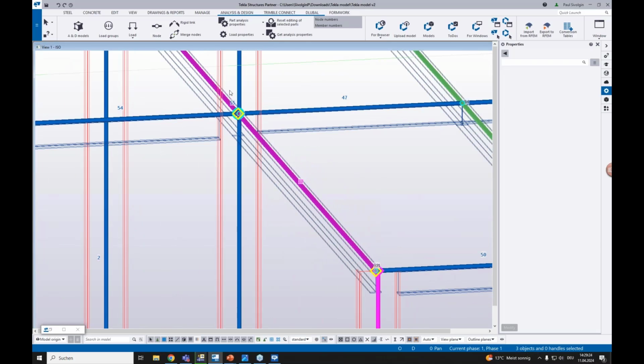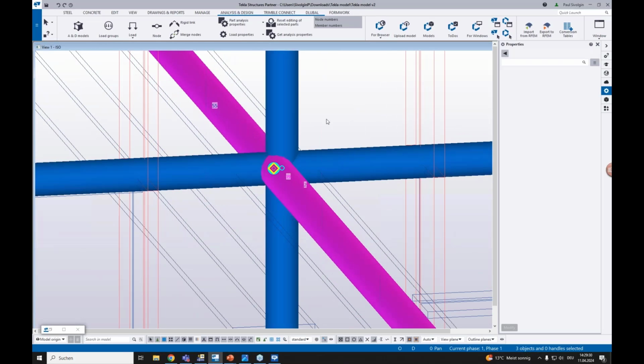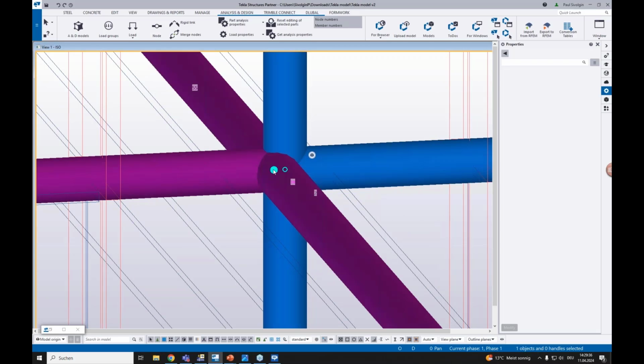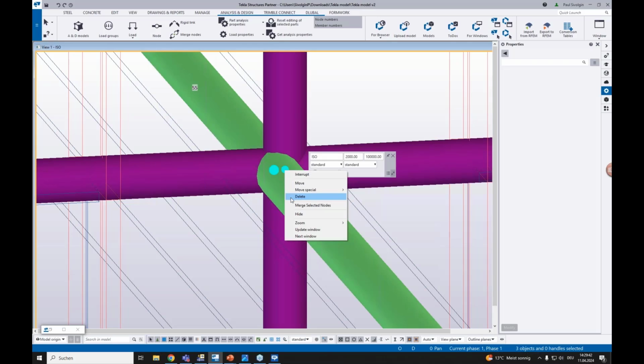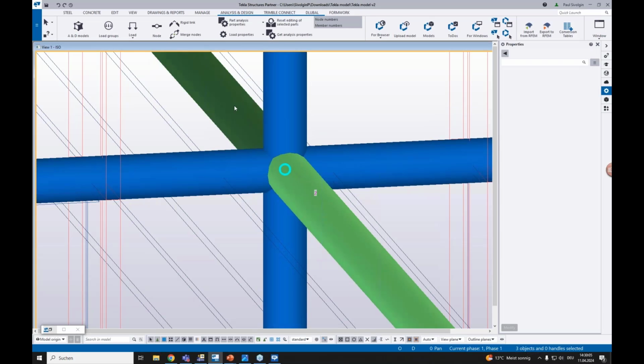And how do we do this? It's better to go back to a point where a lot of members are connected. So in this case, we want to move this connection to this node, and therefore we can just mark these two nodes and say we want to merge selected nodes. We can pick the merge target node, this node. Afterwards, okay, we are not allowed by current settings to move the axis. We say we will allow it for this case, and you see this axis moved.